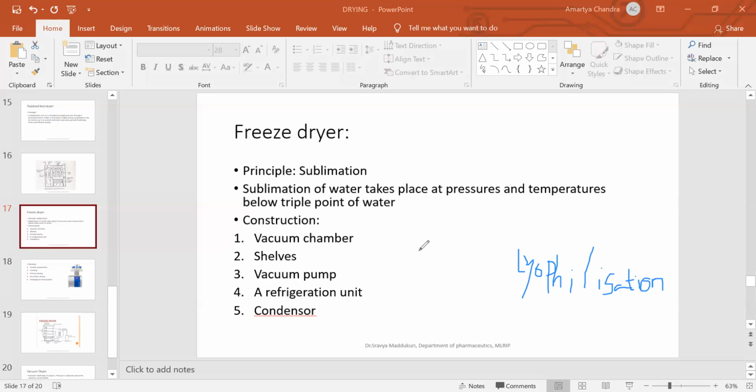Rotary freeze dryers have a cylindrical reservoir that is rotated during drying to achieve uniform drying. In a manifold freeze dryer, a short, usually circular tube connects multiple containers with the dried product to a condenser. I'll show you all the 3.